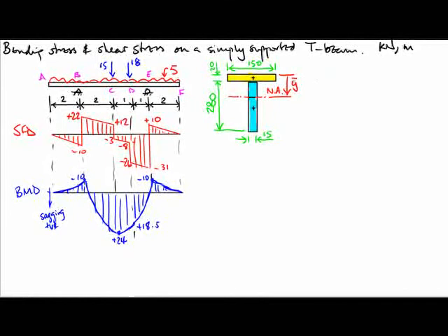and for that we're going to take moments. I'm going to take moments about the top edge. It could be about any edge, but the top is just a convenient place. So taking first moment is area times the distance to the centroid. So I will firstly do it for the individual blocks, and then the sum of the moments for the individual blocks has got to equal the moment for the total section.